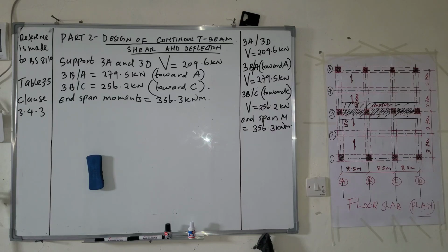Example, number 1, moment distribution method. Number 2, three-moment theorem. Number 3, slope deflection method, such that you will come up with the maximum bending moment and the shear force, and then you plot the diagram for bending moment and shear force, indicating critical values. And then from there, you can design such a beam.